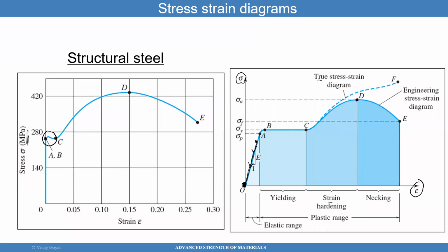So, as you can see here, if you stay in the elastic regime, it goes back to zero. But the minute you start yielding the material, then you're going to start getting some plastic deformation. And typically, when you unload, you're going to unload in this way. Not always, but in many cases, you unload parallel to this curve, to the initial slope. And the same could be here. And the reason is because you're recovering part of the elastic strain that you had encountered.